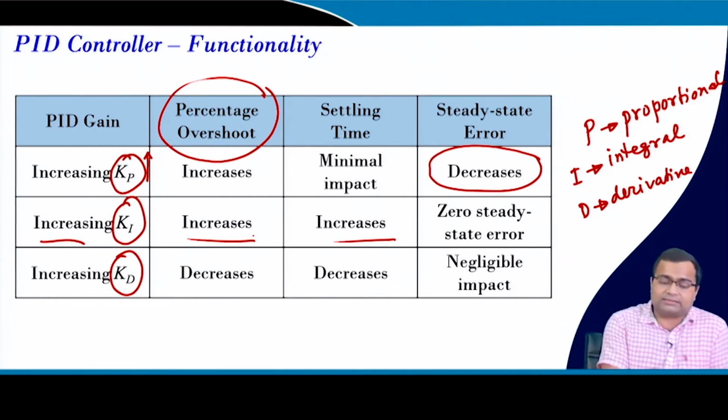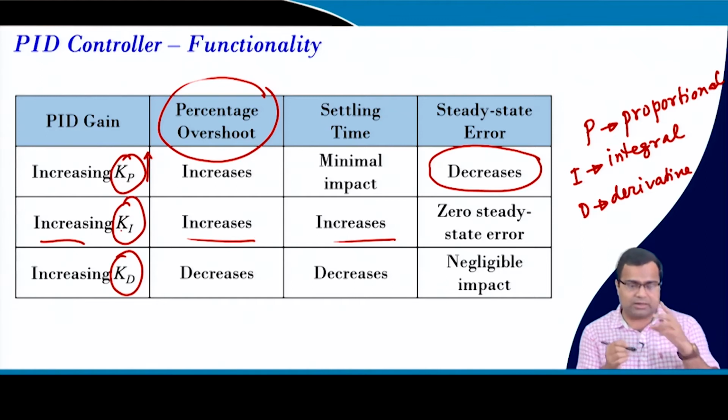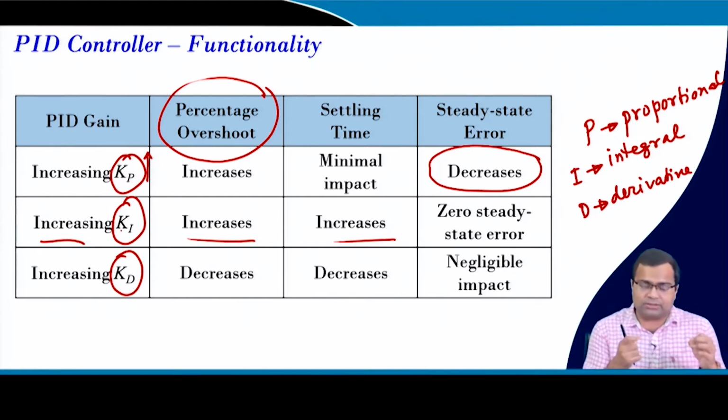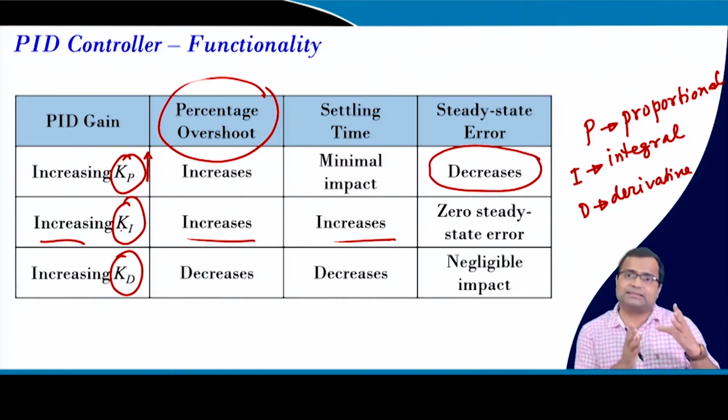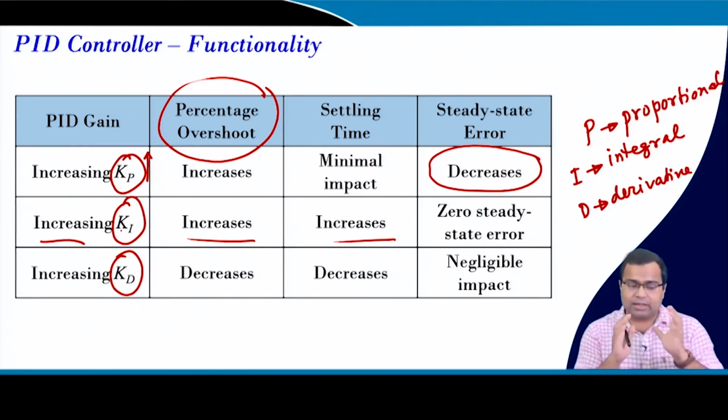But in some cases, when we discuss current mode control as well as voltage mode control, we discuss feed forward action. If you do not consider feed forward action in voltage mode control, we will see the loop gain depends on the input voltage. So, the loop gain can vary when there is a change in input voltage.